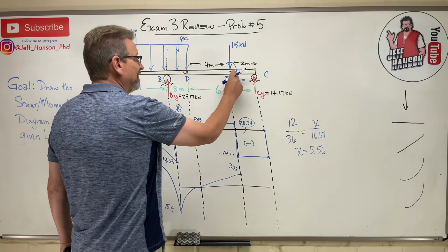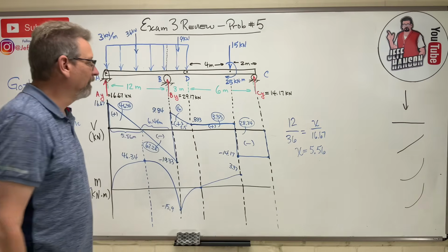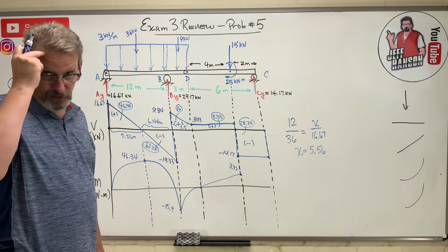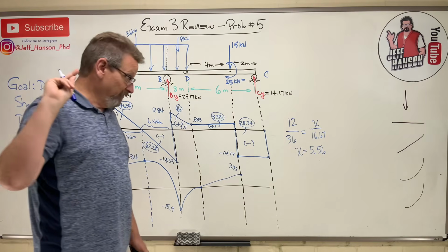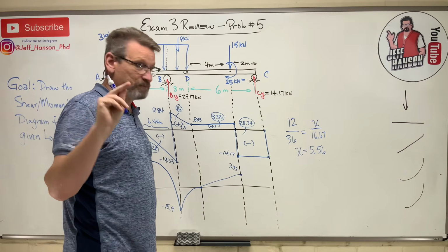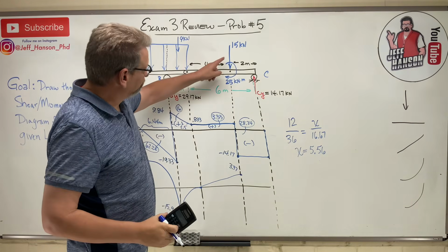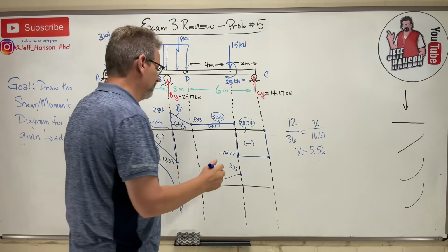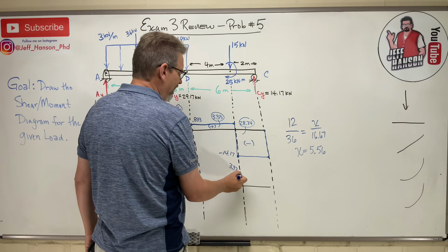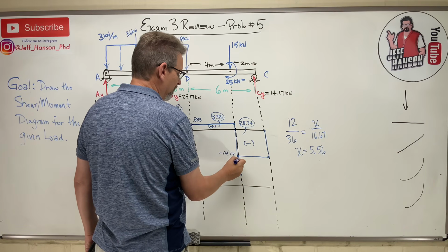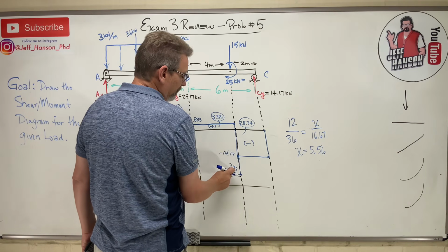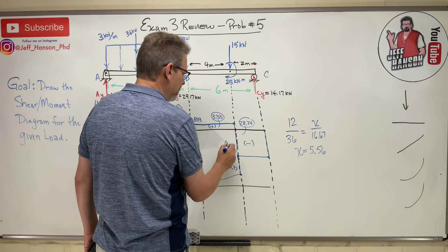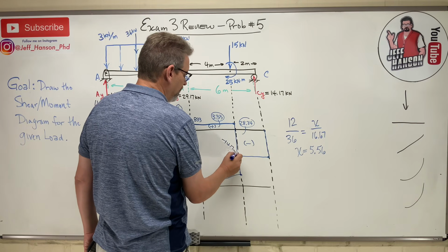And then there's a moment right there, okay? And the moment is 25. And let's see, we remember our little trick. In the kitchen, the clock is above and the counter is below. So that is a clockwise moment. So that means it's going to go up, doesn't it? So it goes up 25, whoop, to right there. And what's that number? 3.33 plus 25 more, right?